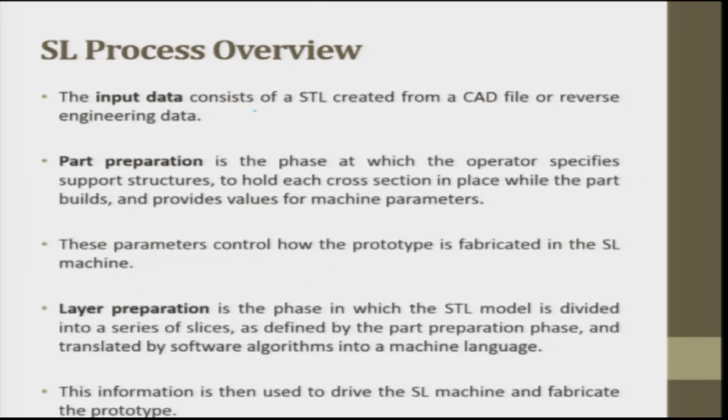The input data consists of STL created from a CAD file or reverse engineering data. Input CAD file. This CAD file, as I told you, has to be a solid model, not a surface model. Predominantly we go for a 3D solid model, or reverse engineering data, point cloud data or MRI data, CT data. That's what we are saying here.